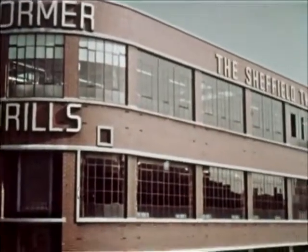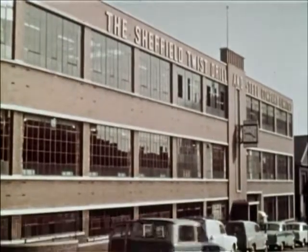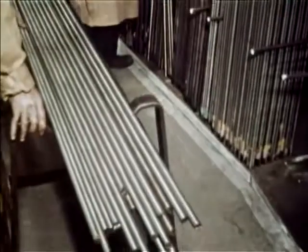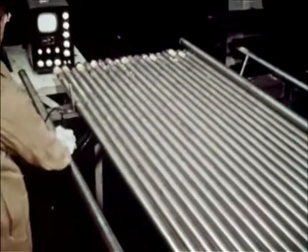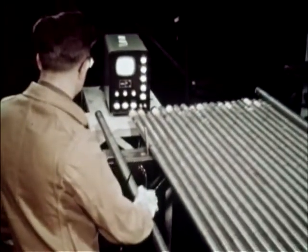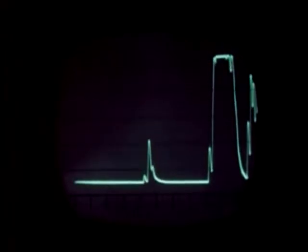At this factory, there is rigorous quality control and inspection at every stage of manufacture. To make sure that the steel used conforms to the company's rigid metallurgical specifications, each bar is critically examined. As soon as they are received, the bars are tested ultrasonically for flaws. This is how a flaw shows up on the oscilloscope. Any bar showing a defect is immediately rejected.